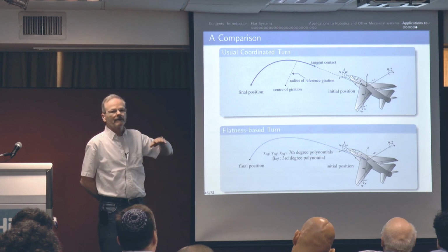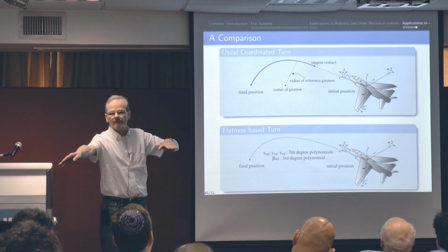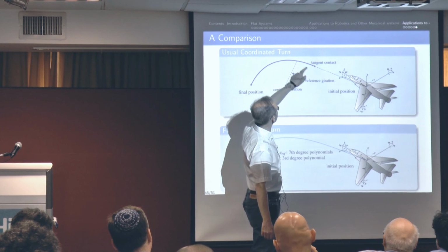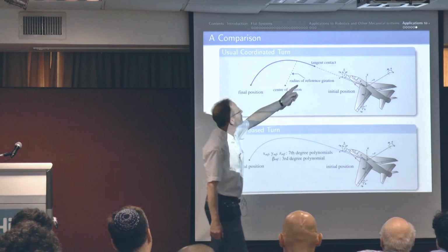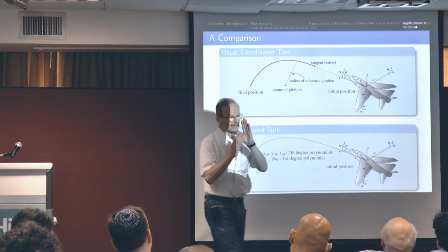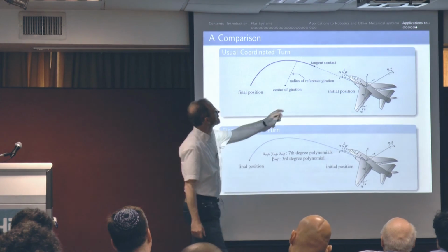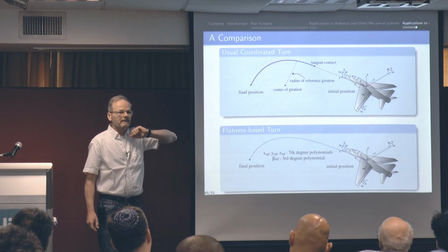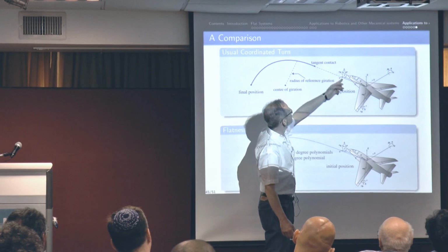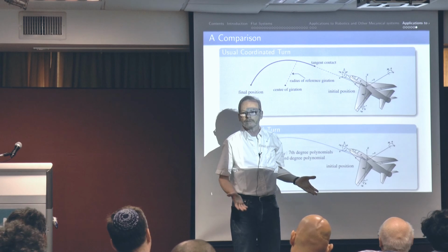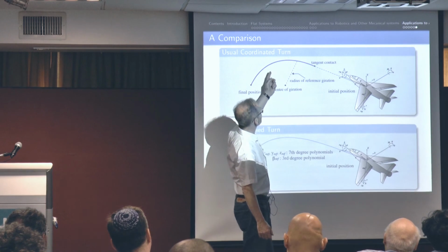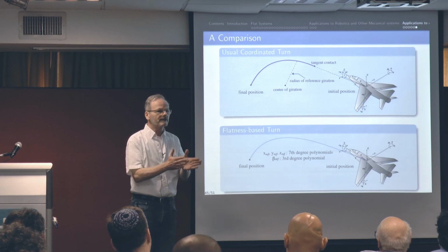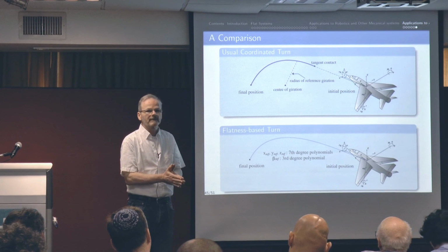You're traveling at constant speed, and you want to make a turn in order to arrive at this point. So you construct a circle with a given radius here, which arrives tangent to your velocity line. And what happens at the tangent contact here? What happens is immediate. This is a line, so the second derivative is 0. This is a circle, so the second derivative is a function of the radius. So there is a discontinuity at this point of the second derivative.